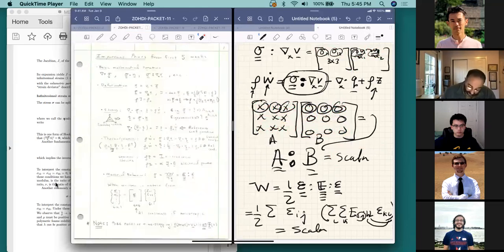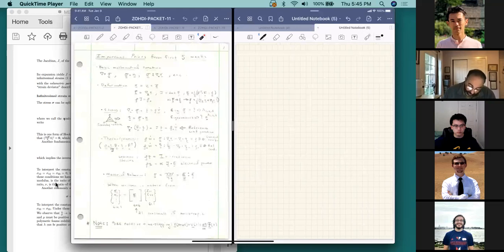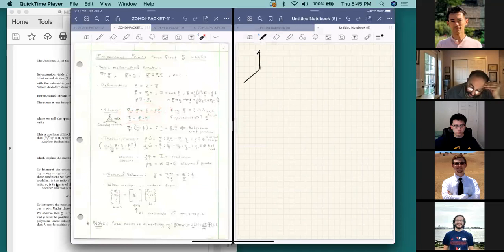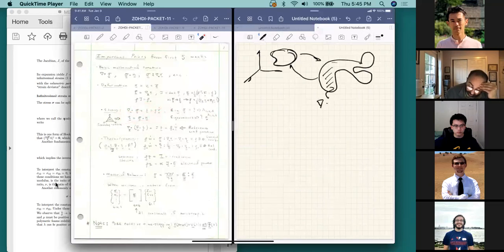All right, well, let's see. So the next thing we had to review is the constitutive laws. We've done the stress, we've done the traction vector, but in many cases, it's not easy, when we consider the deformations of the body, to consider the deformed configuration where the body might have gone through some crazy deformations like this. So oftentimes what people did is they mapped it back to the reference configuration and rewrote the differential equation that lives here, which is the divergence of sigma plus f equals rho v dot.